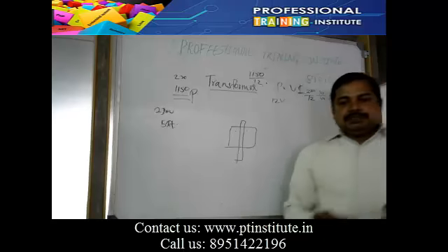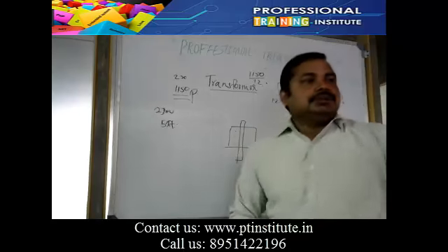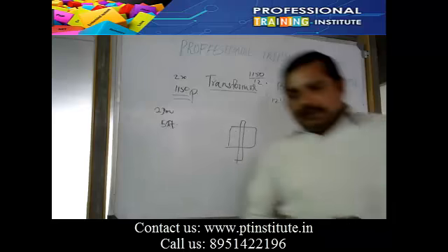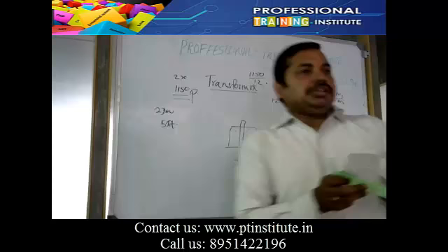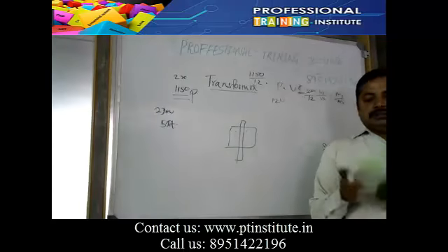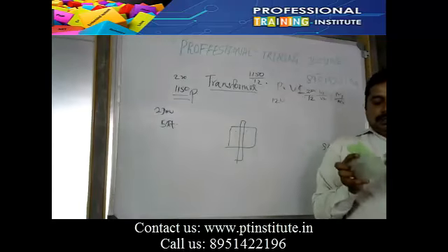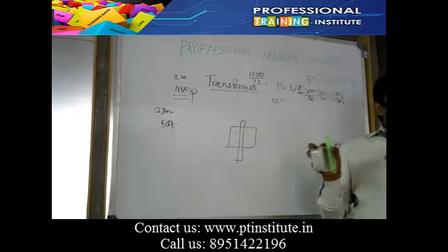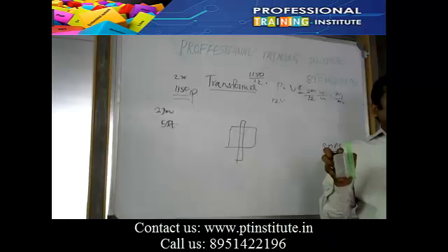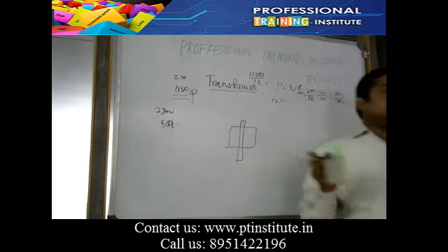Consider this is the PCB, and if you are putting a transformer on top of this, this area will be literally cut in between, because we don't want anything to be transferred from here to there.